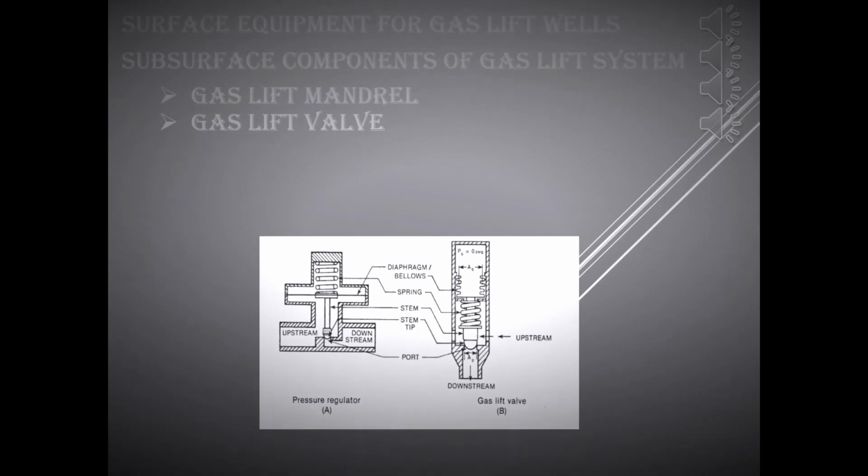However, where greater port area is required because of high volume production, a gas lift valve with a port area larger than 1/4 of an inch should be utilized. Unbalanced, nitrogen-charged, bellows-operated valves with spring can be used for continuous lift wells where the production to be obtained is moderate and when the well temperature is very high with a high geothermal gradient. For high volume of production, this is again not suitable.